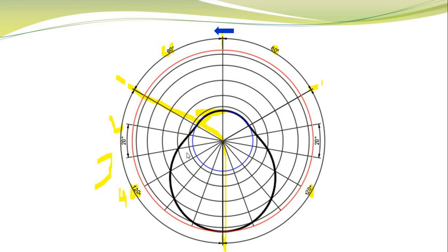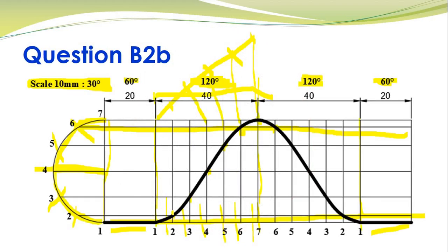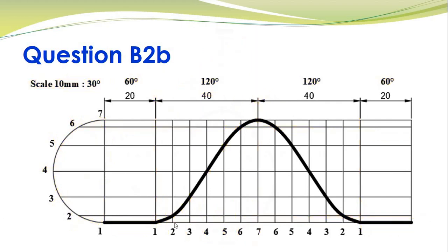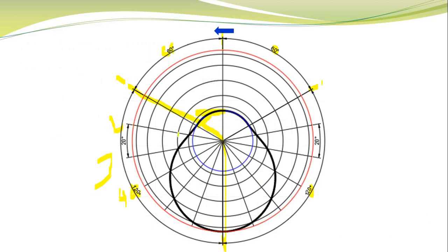Now let's look at point 2. So point 2 is over here, so I measure this distance on my compass, and then this is the radial line for point 2. Taking my distance from my base circle, which is basically your cam radius, so from the base circle, which is blue, taking the distance, cut it on this radial line.